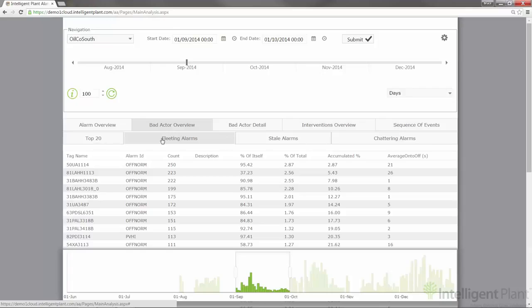Often, when speaking to operators, they will say of this type of alarm, "If that one stays on for more than a minute, then I'll do something about it. Otherwise I ignore it." So why not configure the alarm to behave in a similar way? Most DCSs have delay functions for alarms, so it could be set up to only alarm if it is on continuously for 1 minute. Of course, if this is done, the operator needs to be aware that this is how the alarm works.